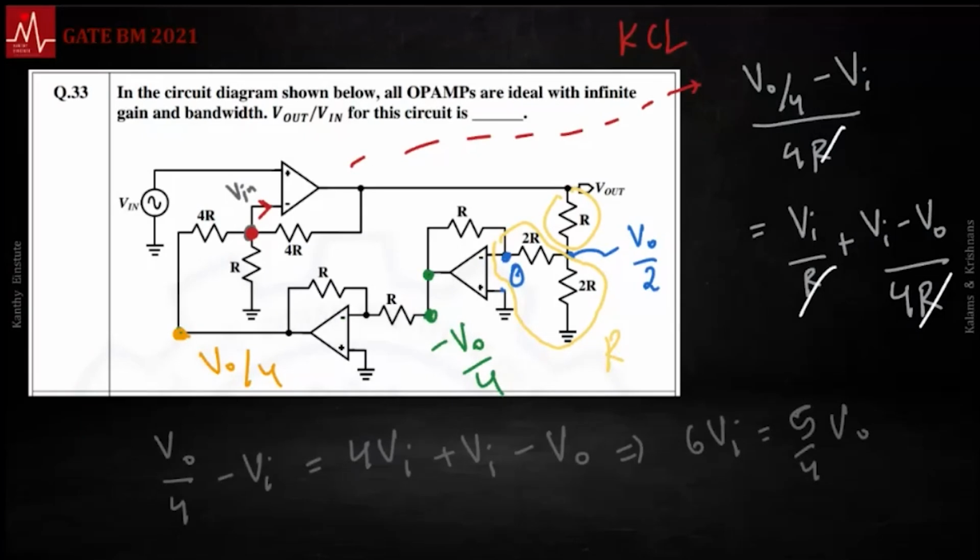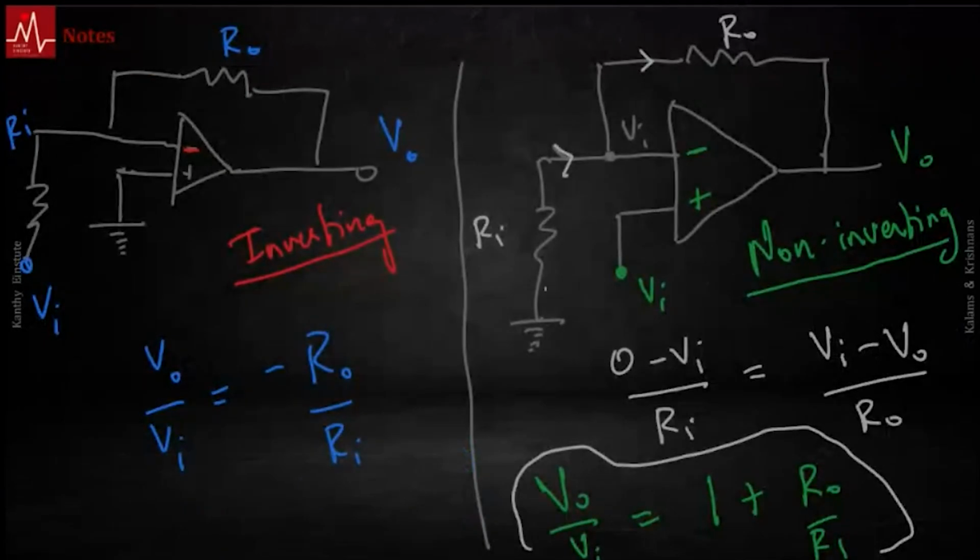So notice, I essentially wrote down one line. If you can recognize the subparts and you're familiar with that, the answer is one line. But this is a problem where I have to look at the subparts and solve it. If I am writing a current here, the voltage division, no current through this input terminal, and you don't recognize this is an inverting amplifier, you cannot solve it and you are going to waste time when you get to the exam. Which is why at least this much you need to know.